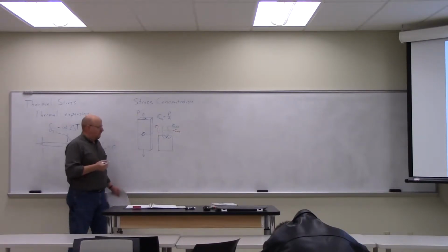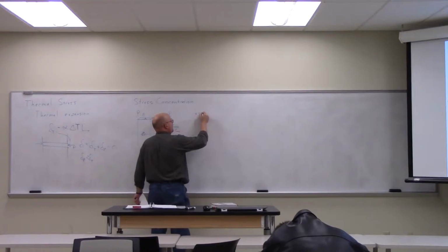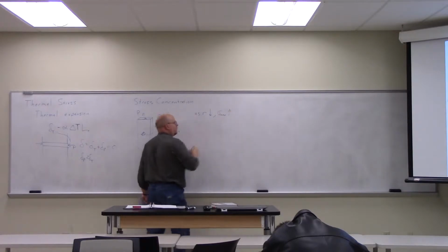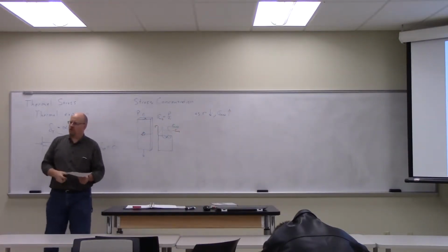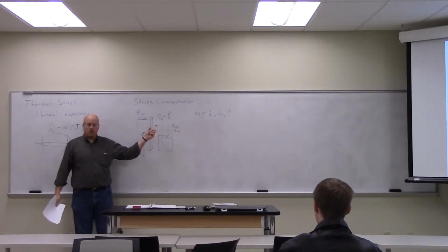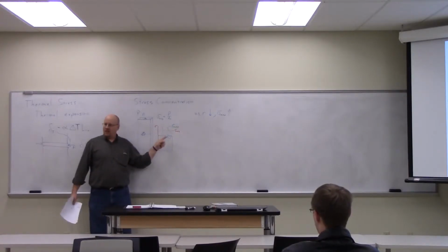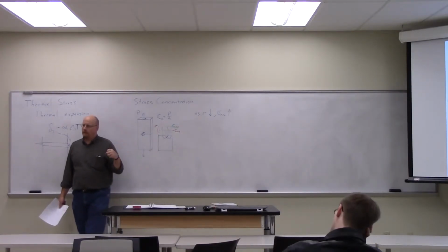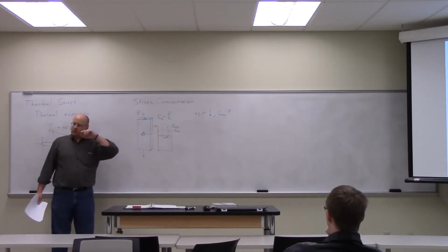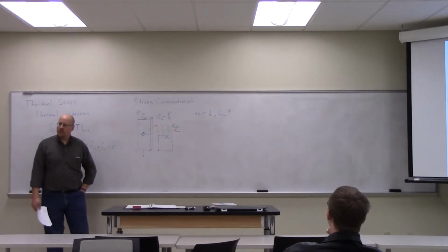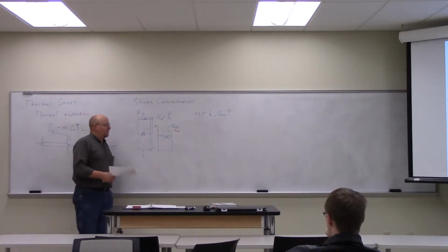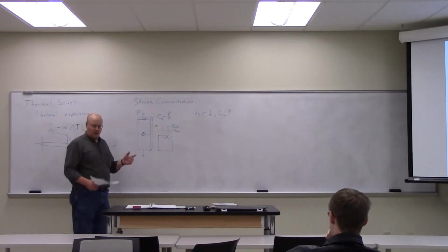And in fact, as r decreases, the maximum stress increases. So there's an inverse relationship. It's not a direct inverse relationship, but as r gets smaller, so that you get a smaller and smaller hole, the stress concentration at the edge of that crack goes up. So a small hole has a bigger stress at its surface than a large hole. Is there a really simple explanation for that? Come back next semester and talk about it in material science. I don't spend too much time talking about it here.